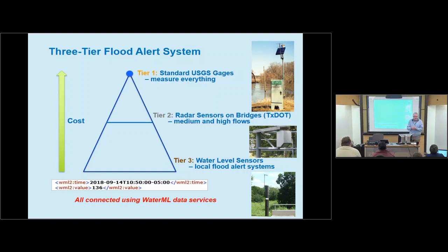Yes? Is there a large water model, like a national water model for water quality? No, there is not. There are aspirations to do a national water model for water quality, but that hasn't worked out yet. One of the things that would help is the geometrical information about volume and area and depth and so on in the river system, because water quality depends on the lag time, or how long the water spends in a particular reach. If we can start to quantify that better with the channel geometries, then our capacity to do water quality modeling is going to be significantly improved.